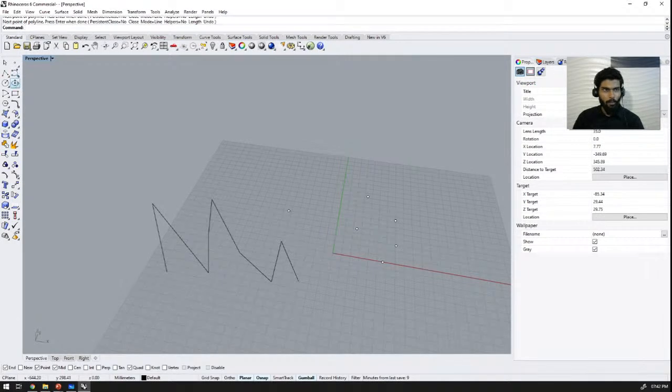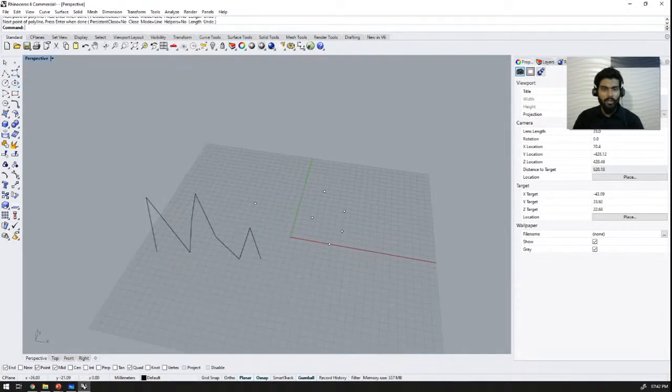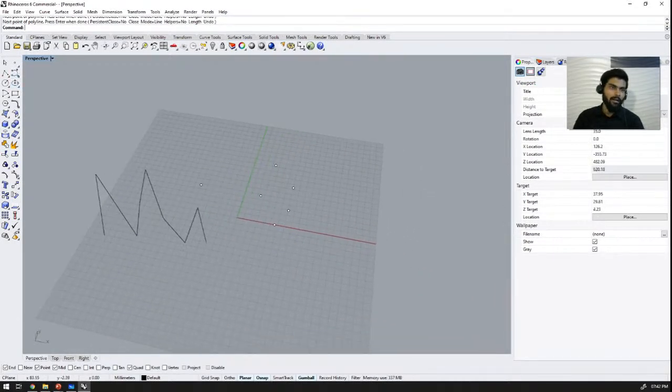So these are basically polylines, and then there are curves. Let's talk about curves. Curves are very interesting, and in Rhino and Grasshopper you can make organic stuff very quickly, very effortlessly. In order to make a curve, there are two types of curve in Rhino. The first one is interpolate curve, or interp CRV. The command is interp CRV. You can also activate it by using the second option here in the menu.